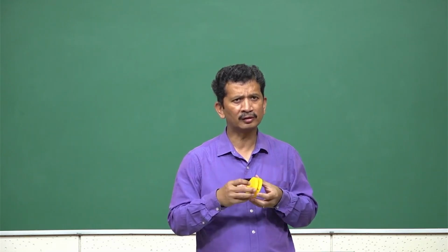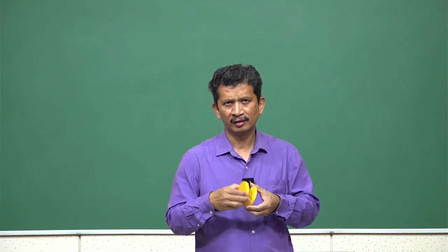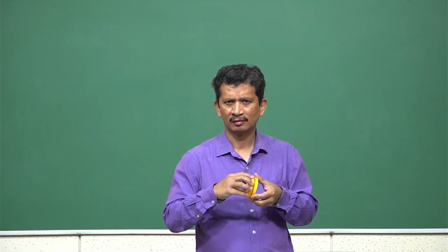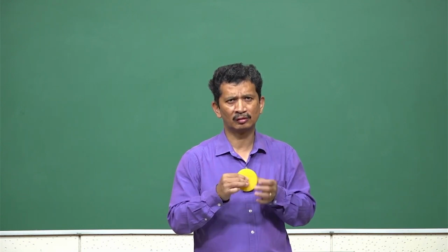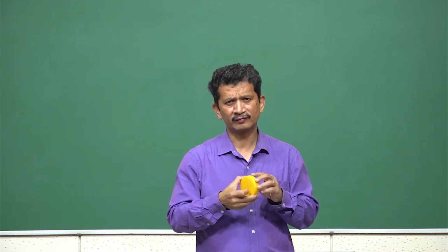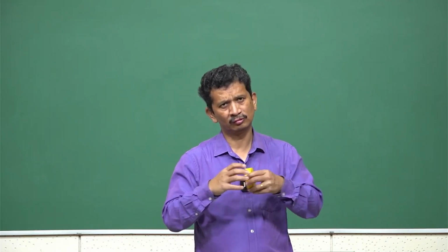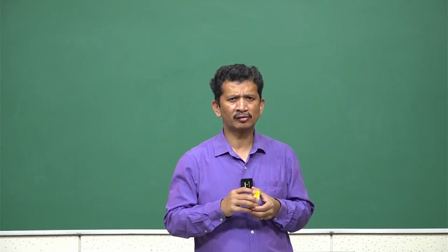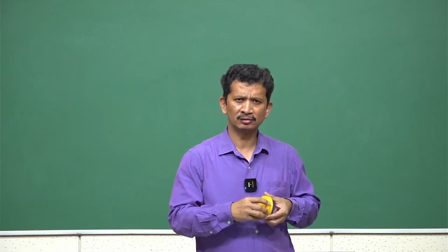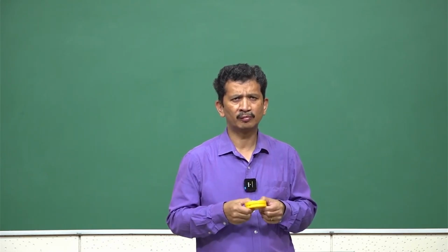I do not have to even look at the part, and what I will see is it's always defined, and if these V's are well defined, it will always go to the same location. So, I do not have to even align it. So, if it's cylindrical surfaces, and if you want to align the two axes to two shafts or to any cylindrical objects, and if you make this kind of features, they will always go to the same locations, and later I can use the bolts or the clamps to lock their position.